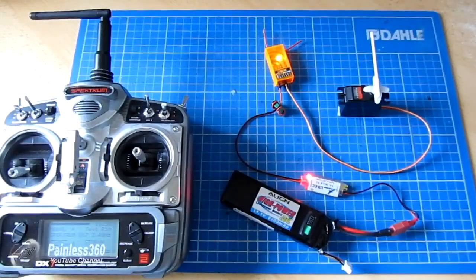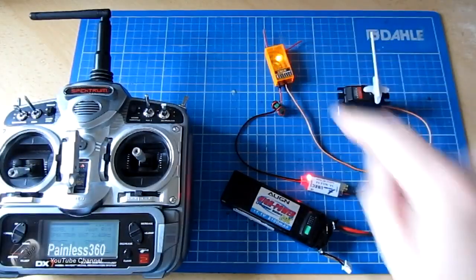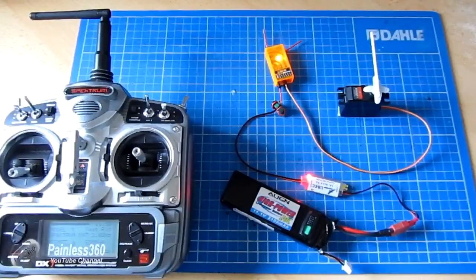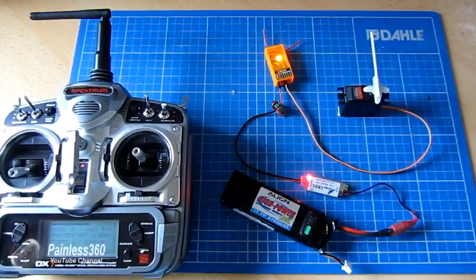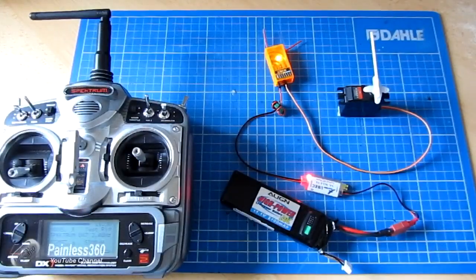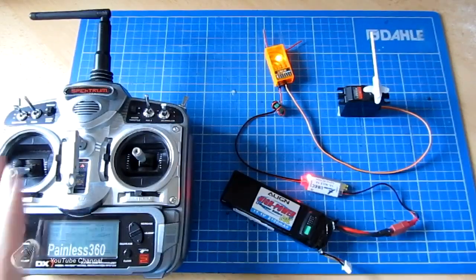The spread spectrum technologies that most of the modern radios use these days not only use 2.4 gigahertz and different bits of the 2.4 gigahertz band, but are also using digital communication to make sure that the signals that are received in the receiver are right and are error checked. So if anything wacky goes on with the radio, the receiver knows about it. And this information is sent in frames or packets of information.